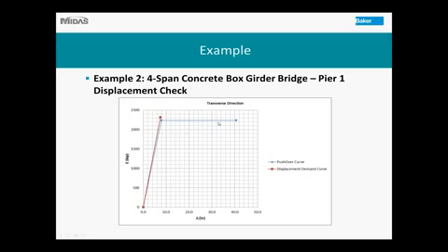The blue curve here shows the pushover curve, and the red curve here shows the displacement demand. So this column barely yields. As you can see, it just exceeds the Mp by a little bit. And if that is the case, it means the elastic force in your model is going to be your design force.